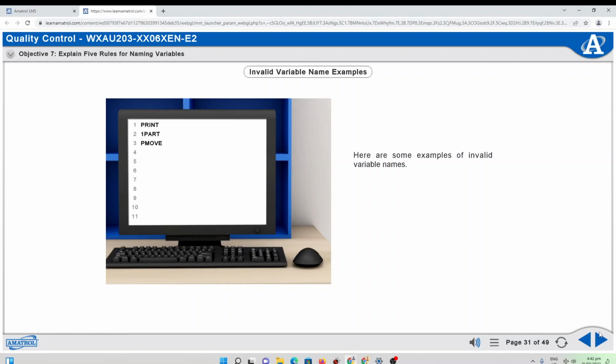Describe the operation of the operator interface commands print and printline. The MCL language has 2 commands that allow the robot to output information to the computer monitor: print and printline. The print command outputs messages or the contents of a variable from the robot controller to the computer screen. The message that will be output to the screen is enclosed in quotation marks. The content of a variable is displayed by following the message with a comma and the name of the variable.